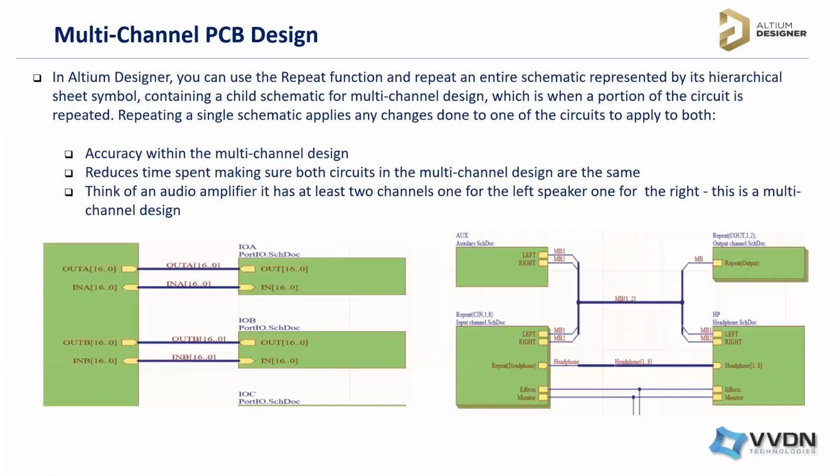Then multi-channel PCB design. In Altium Designer we can use the repeat function. Previously, suppose we were trying to add a sheet to our schematic and it was repeating, like a power supply portion, so we had to add two or three sheets like that.